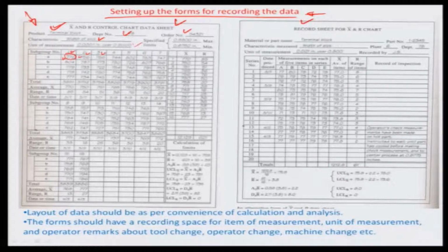So the coded variable here is really that it is 0.800 inches plus the factor which has been given, 0.0001 inch, times the observation which has been recorded. This is an easier way rather than writing a decimal place and writing the whole values. You are trying to have a coded variable into the picture. So this is how you lay it out.